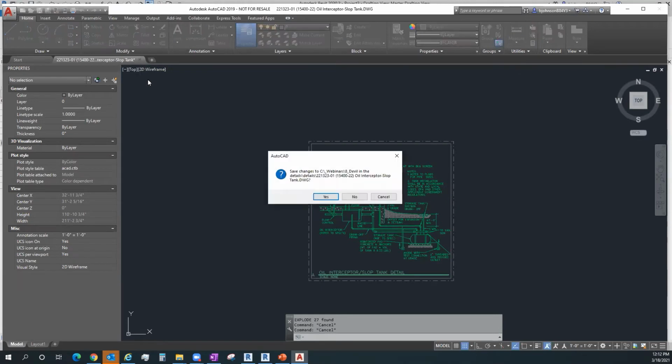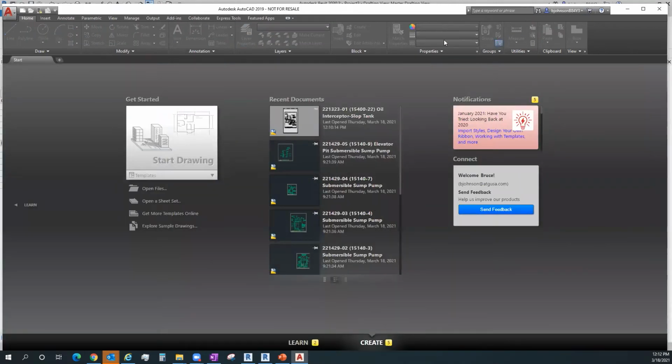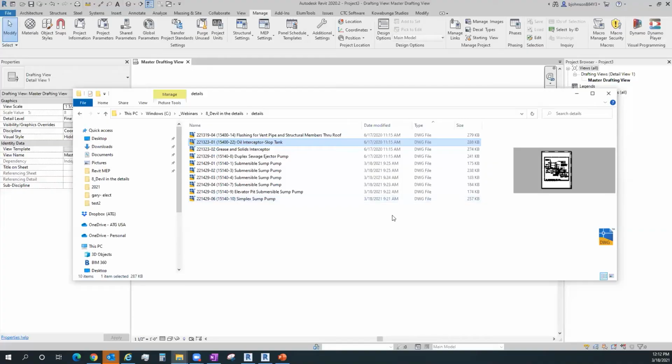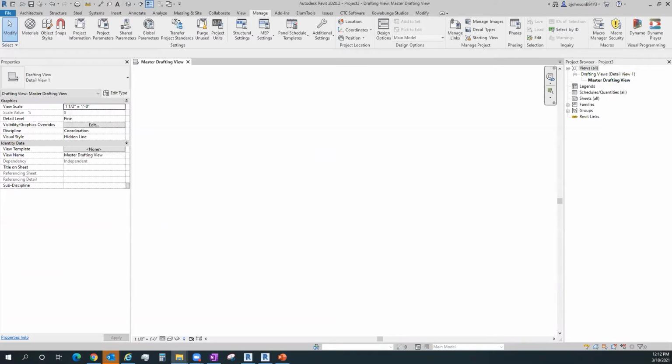I'm just going to kill that because I've already done some of this work in my Revit session. So anything that's additional blocks in there that, once inside Revit, turn into more blocks that need to be exploded more than one time, those are things that I need to be a little bit cognizant of. I could go back after doing an initial conversion and do a fix on those on all the rest of my CAD drawings before I would import them. But usually I'm going to do at least one conversion completely manually first, and then I'll actually know.